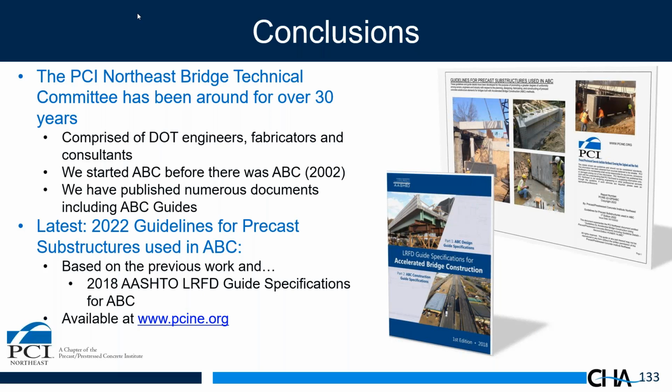You still do your same design of the pier. It's still a reinforced concrete structure, and we are designing these connections to emulate cast-in-place construction. For virtually every connection we showed today, the connection design is very straightforward using the forces acting on those connections. And really, people are mystified by precast. It's really not that hard to design these things. When you open up the AASHTO guide specification and read the provisions, you'll probably say, wow, that was a lot simpler than I thought it was going to be. And for some of these connections, like these socket pocket connections, the design barely changes from cast-in-place.